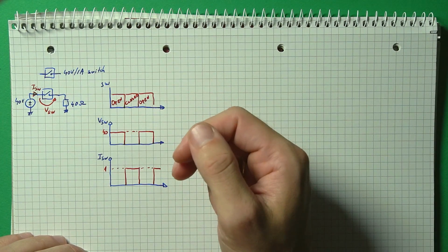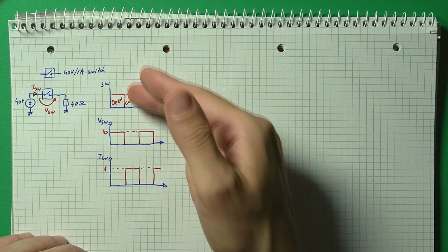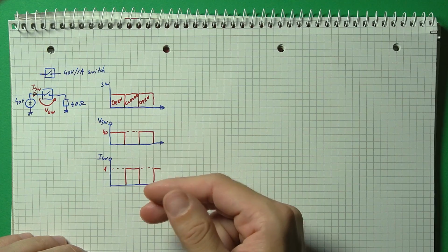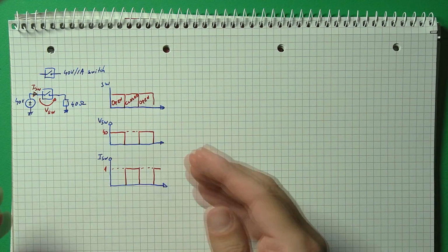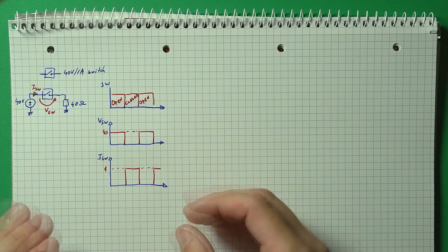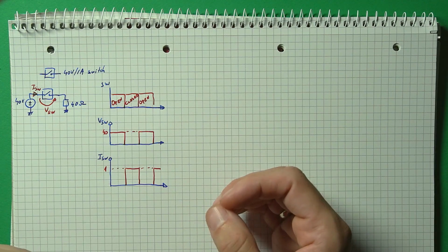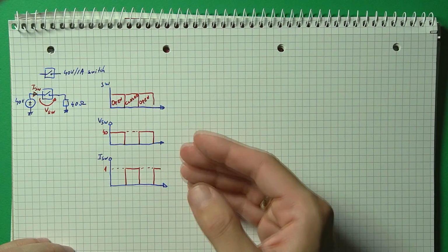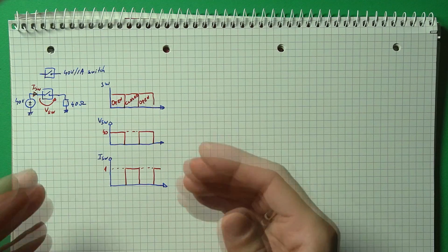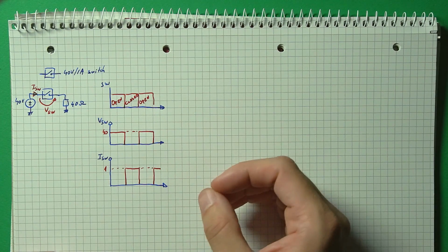When the switch is open, there are 40 volts across its contacts, and when it's closed, there is a 1 ampere current running through it. So when driving resistive loads, it's very easy to choose the right switch if you know the supply voltage and the load value. With this information, you can always determine the exact voltage and current that the switch will see, and choose the first switch that is equal to or preferably rated above that.